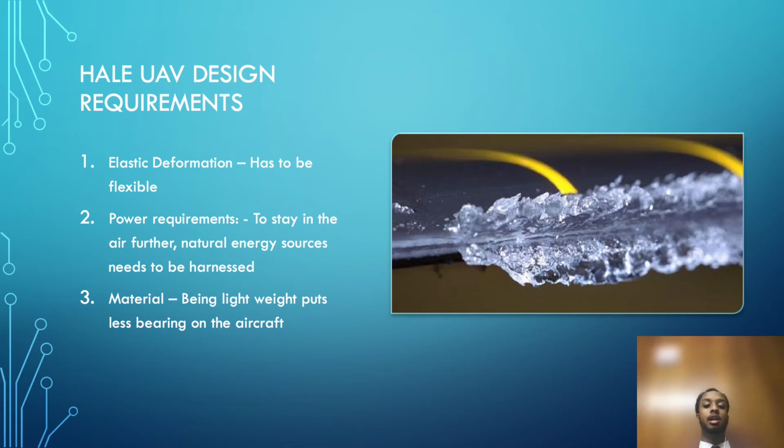Now, since my aircraft will be up in the sky for a long period of time, the most important design requirement is to consider how I could keep it in the air for the longest amount of time. Why is that? With the aircraft being lightweight, there's less load on the aircraft, allowing an increase in the storage of things like fuel or fuel cells when it comes to my solar HALE UAV.